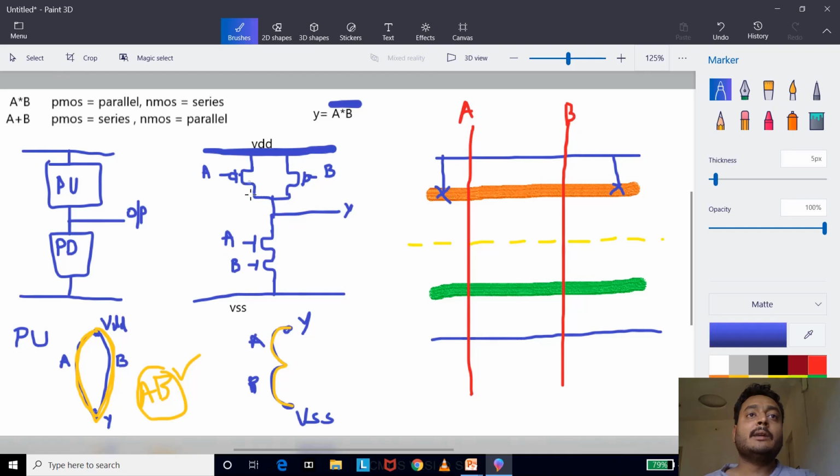As I said before, here A and B together can be connected to Y, or A individually and B individually can be connected to Y. You can see A and B are already available together like this. So you take the connection from here, and where should you go? You should go to output Y. So you take this and connect it to this as the output, say Y. Any intermediate connections? There are no intermediate connections because we have only two transistors. You will see that in the next examples with more variables.